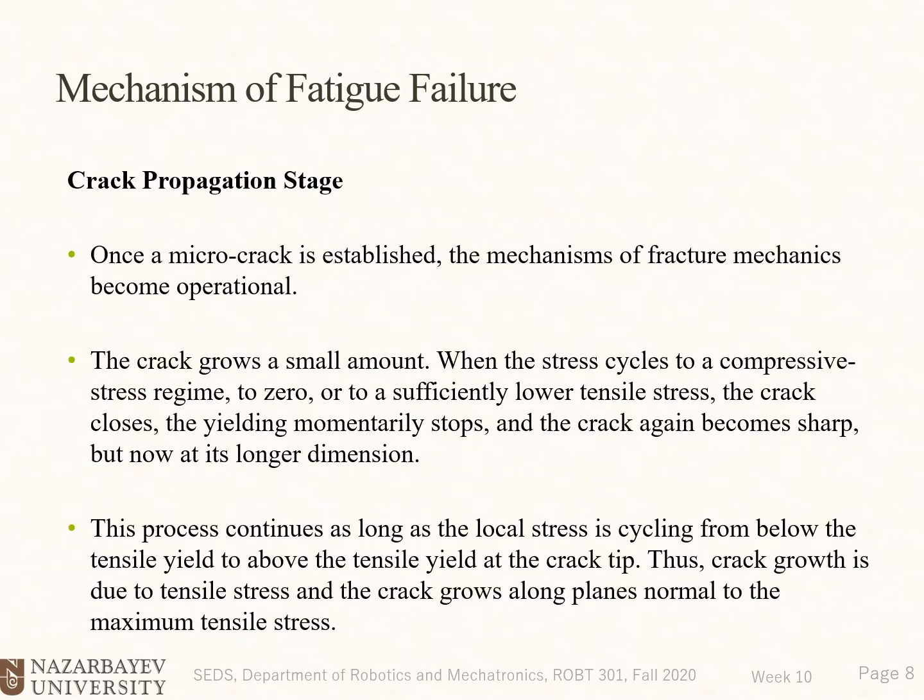Then we have crack propagation stage. Once a microcrack is established, the mechanisms of fracture mechanics become operational. The crack grows a small amount when the stress cycles to a compressive stress region, to zero, or to a sufficiently lower tensile stress, the crack closes. The yielding momentarily stops and the crack again becomes sharp, but now at its longer dimension.